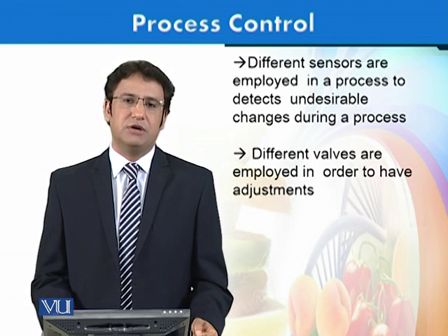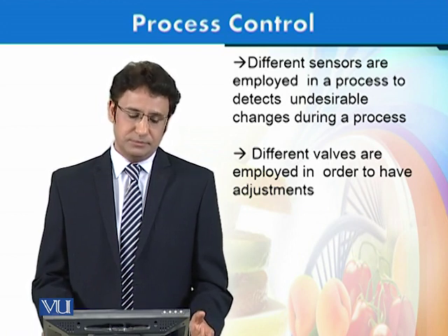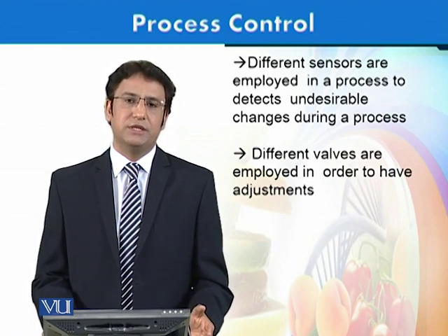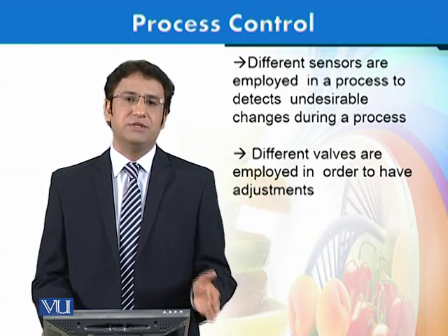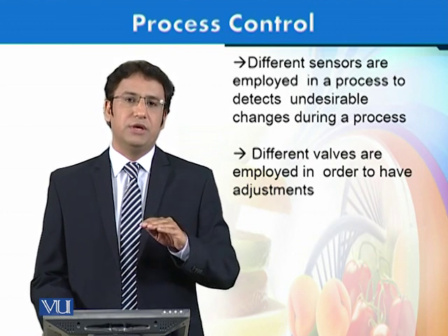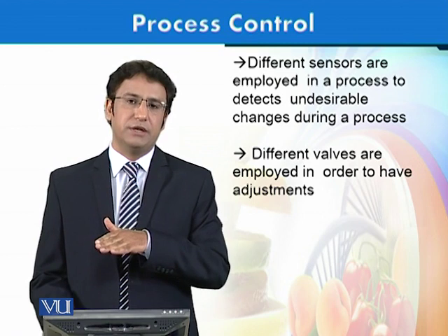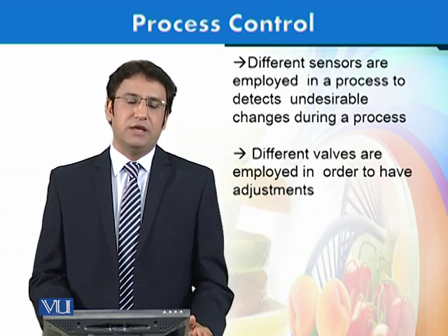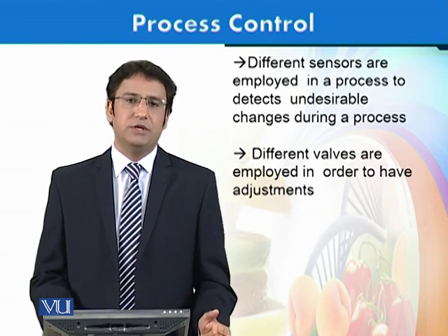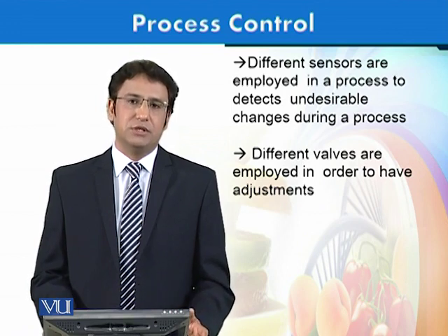If it's desirable, the process would go on as normal. But whenever there is a deviation in the temperature, or whenever the temperature is lower than the required values, there would be flow diversion valves. That means this milk would not go to the final product; rather, it would be turned back into the processing line to be heated again. That makes sure that every product that passes through that endpoint is properly sterilized or pasteurized, whatever is desired from that end product during this process.